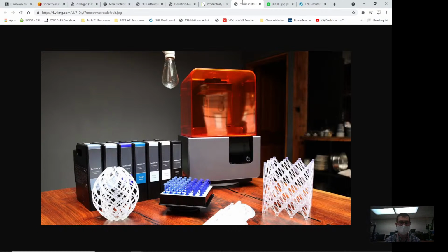You may have saw one of the pictures I jumped over. We have 3D printers. This is one of our SLA printers. It uses liquid for its 3D printing, and one of the things that it does differently than the FDM is that it provides an exceptional level of detail, and it provides a chemical process so students can actually see the mechanical process on our FDM printers, which is our traditional plastic extruded printer, to our chemical activated SLA photopolymer with UV resin hardening type of chemical reactions that we can talk about. It's also used professionally in the labs, as well as like dental, jewelry, medical, and so forth. So it's just nice to see this in the lab here.